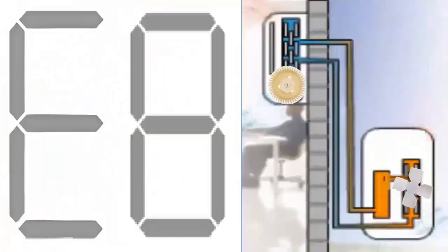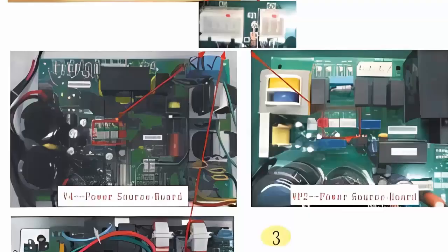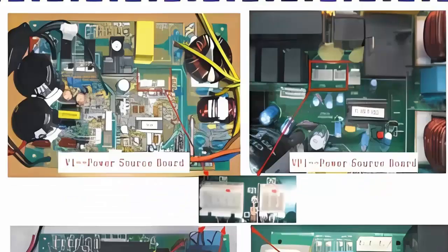8. If replacing the sensor does not resolve the error, it is very likely that the problem lies in the electronic board of the outdoor unit. In this case, it is recommended to conduct a visual inspection of the electronic board to check for any abnormalities.